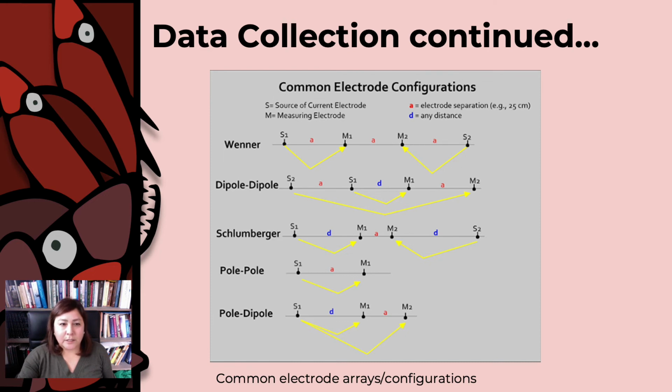Data points are collected by inserting probes into the ground at regular points along transects marked by tapes. To identify graves, we recommend taking readings every 25 centimeters along transects spaced 25 centimeters apart. Transects can be walked bidirectionally, like a zigzag, if the instrument is left in the same orientation. This shortens the time needed to survey, though it is still relatively slow compared to other techniques.